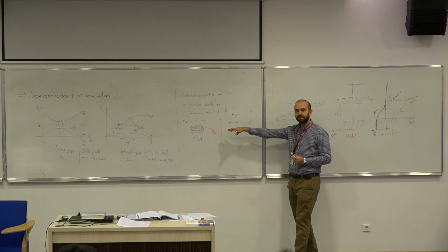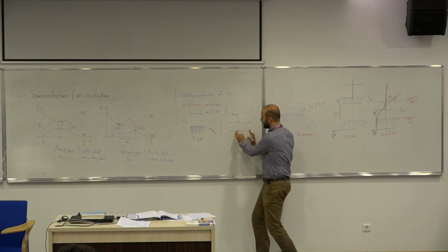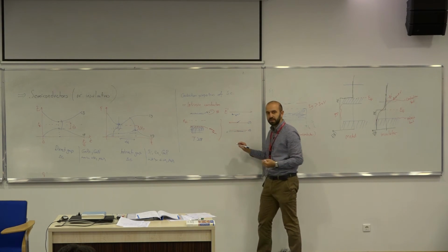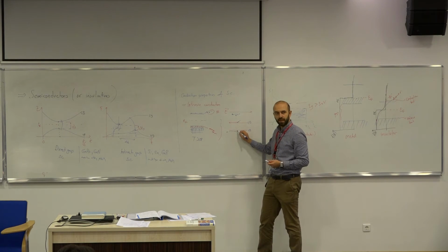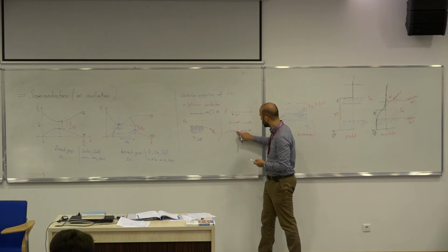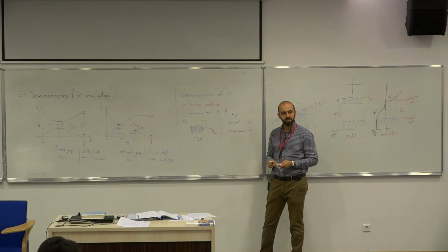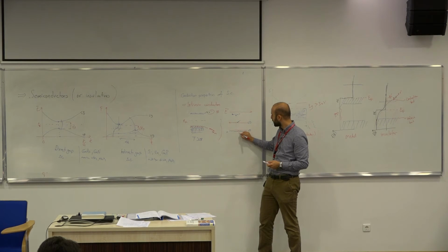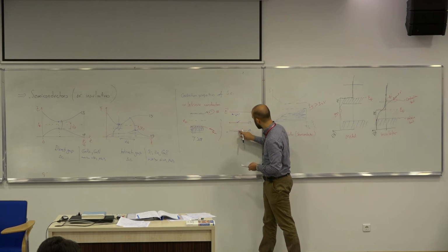Now, as I apply the electric field, all the electrons will want to move in this direction, but there are no available states to the left of them. But this guy is lucky. It can move here. There's an available state here. So if I move one frame forward, this is what I will see. So this absence of electron actually moves in the opposite direction. In the second frame, this electron is now the lucky guy.